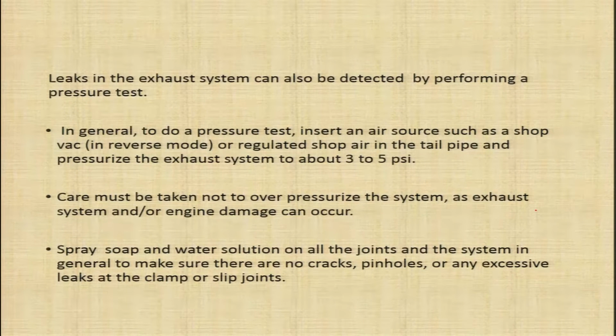We seal the complete system and check with a soap and water solution, or by submerging the exhaust system in water, to see if there are any bubbles indicating leaks. Care must be taken not to over pressurize the system, as exhaust system or engine damage can occur.